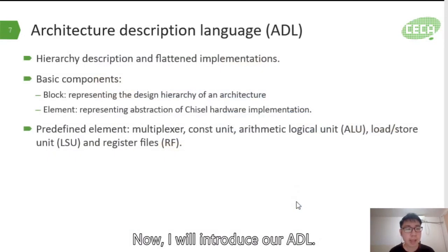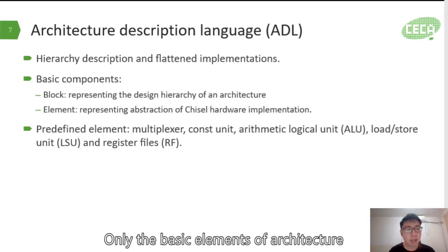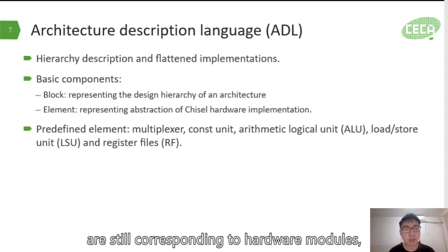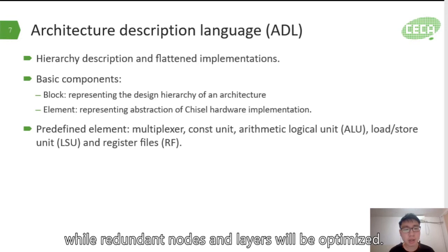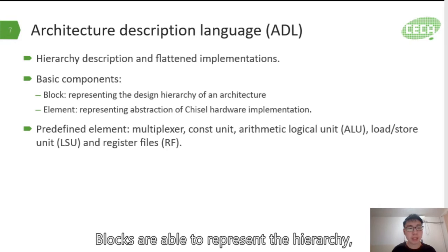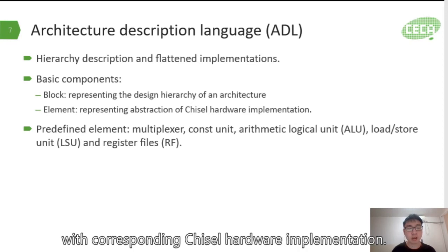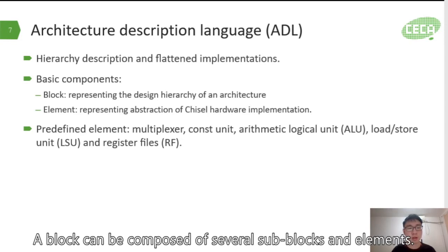Now I will introduce our ADL. We employ a hierarchical design and a flattened implementation method in our framework. Only the basic elements of architecture still correspond to hardware models, while redundant nodes and layers will be optimized. Blocks and elements are basic components in our ADL. Blocks are able to represent the hierarchy, and each element shares a particular ID with the corresponding Chisel hardware implementation. A block can be composed of several sub-blocks and elements.